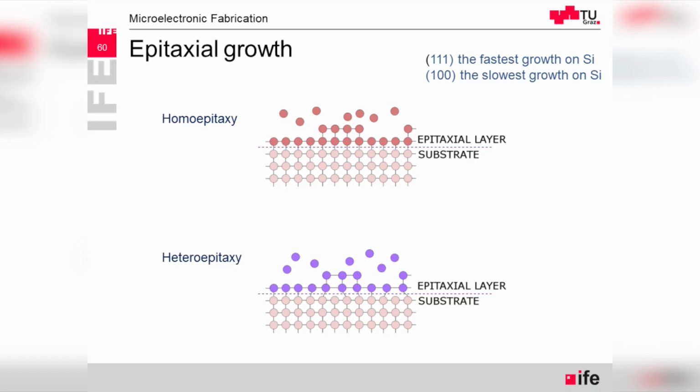That has advantage because the lower in the substrate, where we have high doping, then the conductivity is good. If there is some substrate current, there will be low voltage drop. So for avoiding latch-up in the circuits, that's one trick. It's an expensive trick, but that's to use an epitaxial wafer.